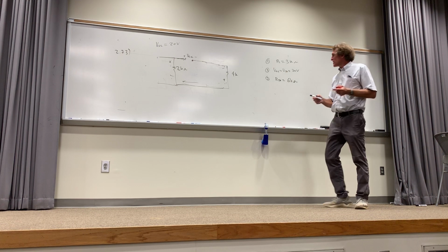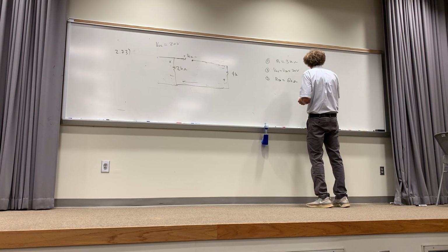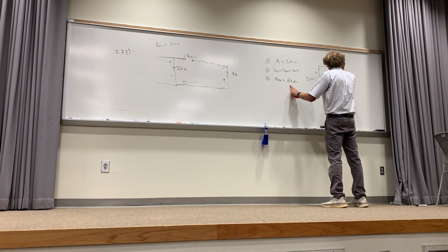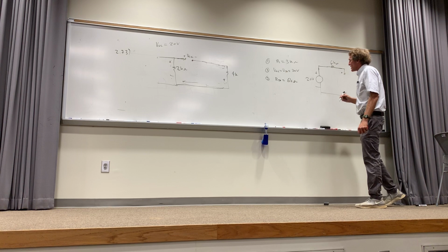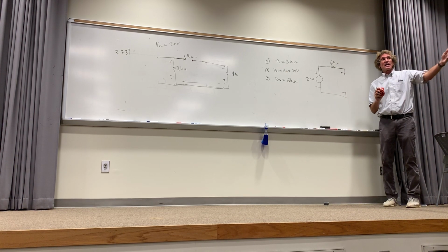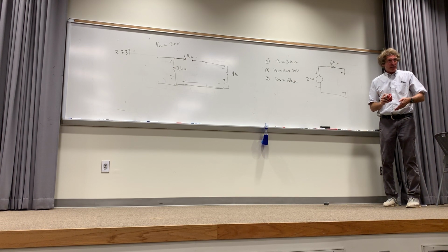Now build the circuit. So what does the circuit look like? You put the open circuit voltage here, which is 20 volts. Then you put the Thevenin resistance in series with it, 6K. Now, that's your plus, that's your minus terminal. I've just built the Thevenin equivalent circuit to everything, and now I apply the load back in.